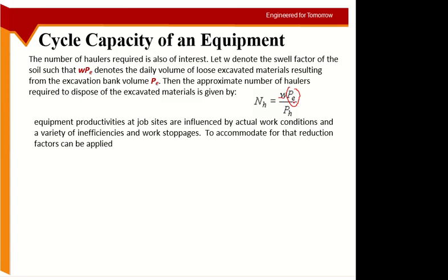So you are taking this much compacted material daily, excavating it. So this is the excavated productivity multiplied by the swell factor. So how much this will become when it goes into the truck in the loose form, and then you divide by the productivity of the hauler for 1 day.